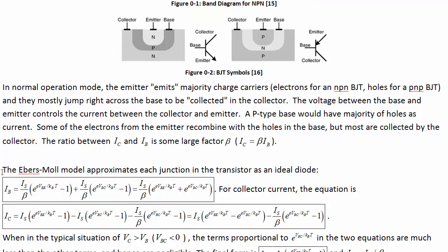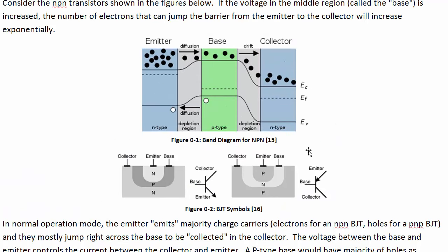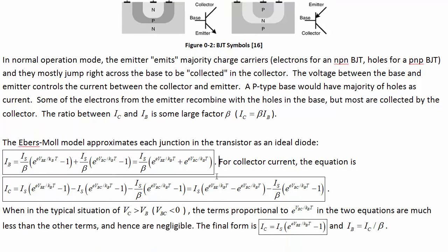All right, we've got a model for how the transistor is going to behave called the Ebers-Moll model. I'm not really going to be picky about how you say that. So let's say Ebers-Moll model, we've got base current is equal to this collection of diode effects. So we've got a base emitter diode and we've got a base collector diode, because it is still a diode from base to collector, and if we were to apply any arbitrary voltage, then you could see why the base current may depend on both of those junctions. And adding those up together, the ones cancel, so we end up with this.